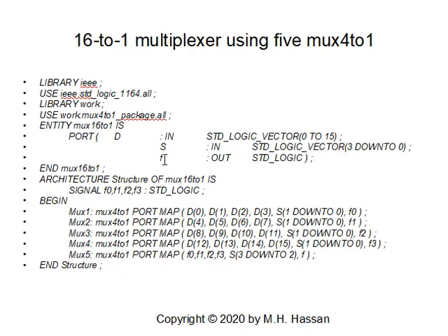For instance, I would like to build a 16:1 multiplexer using 5 MUX41. We've done this in another lecture on multiplexer expansion. Please refer to it. I do have a block diagram, and I refer to this block diagram to design this 16:1 multiplexer. Since I have a package, I will use work.mux41_package.all to link the package to this program.